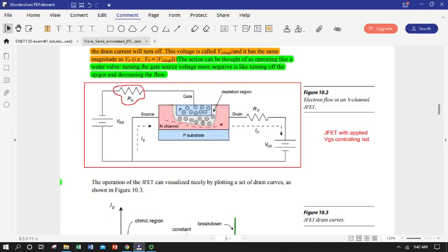Well, as we all know, without those extrinsic charge carriers, that n-type material can't conduct very well. So what we're doing is effectively growing a big resistive gate, a valve, so to speak, out into that n channel. And so the cross-sectional area, the literal physical cross-sectional area for current flow, shown here with the red dotted arrow, goes down.